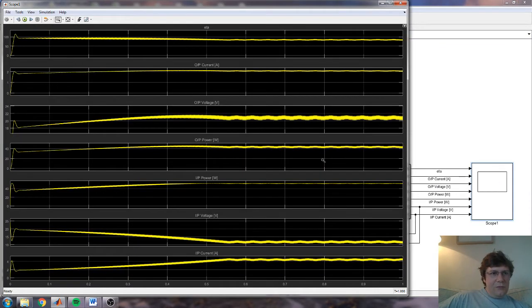And if we go and have a look at the characteristics, we can see that there's an efficiency greater than 100% there, which is obviously not true. I wish it was, I could just retire. The reason for that is if we look at the powers, you can see there's lots of energy comes in this first little time period here. Let me zoom in.